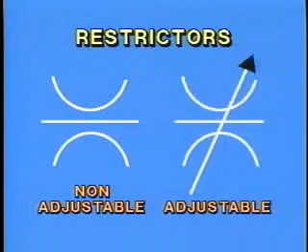The basic flow control symbol is a representation of a restrictor. If the restrictor is adjustable, a slanted arrow is drawn across the symbol. The restrictor could be a special fitting with a small hole in it, or a small drilled passageway within a valve.